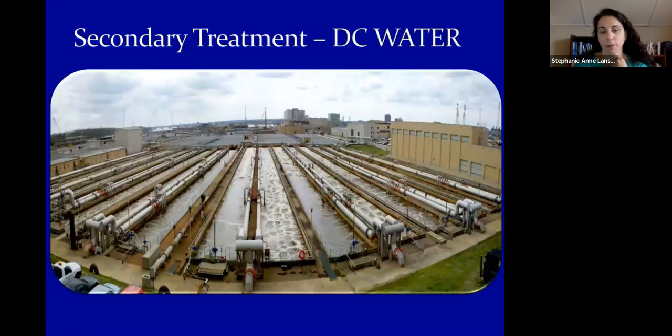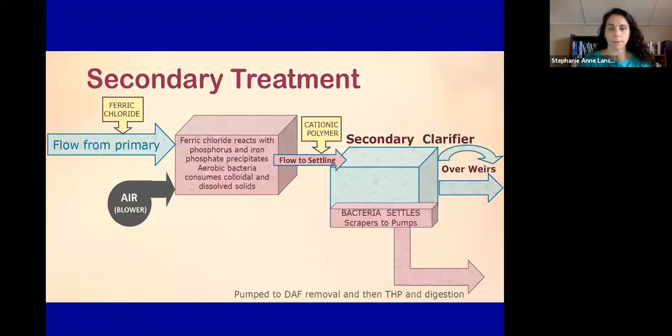And this is a picture of secondary treatment. See the aeration, all the pumps. This is what's being aerated, and again, our microbes are doing it. And then we're going to recycle those microbes through the process as we treat our sludge and break down the carbon through microbial degradation with aerobic microorganisms.